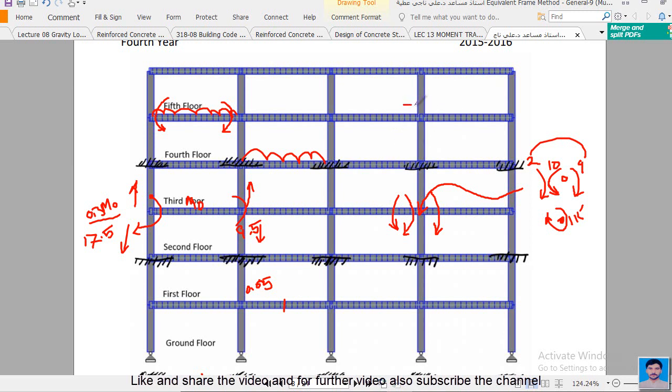When you have an unbalanced moment, the shear caused by it is not acting over the centroid of the column, it is acting somewhere else. Because it is not fully mentioned in the ACI code, we assume that we have already determined the critical shear parameter.